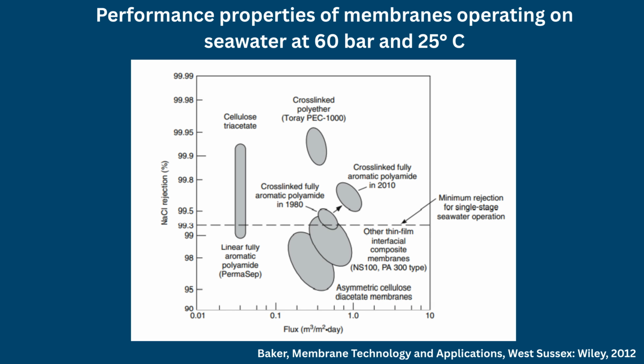Reverse osmosis. Cellulose triacetate membranes dominated the reverse osmosis industry for nearly 2 decades owing to their excellent selectivity, chlorine resistance, and chemical stability. Unlike aromatic polyamide thin film composite, TFC, membranes, cellulose acetate tolerates continuous exposure to residual chlorine, reducing biological contamination and simplifying cleaning protocols.